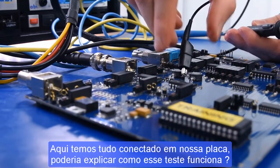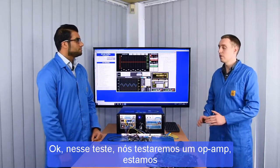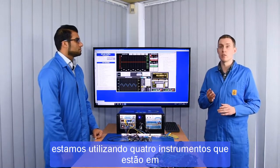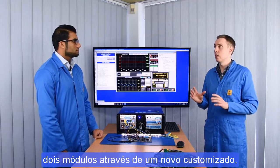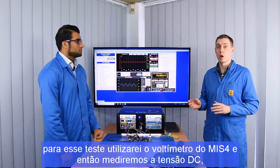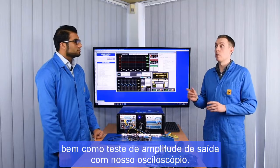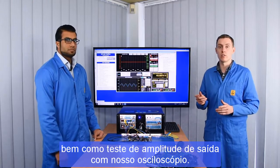So now that we have everything connected to our PCB, can you explain to us what this test is doing? Okay, so in this test we'll be testing an op-amp. We're using a custom instrument. We're using 4 instruments in total from 2 modules combined into 1 custom instrument. We've also added some scripting which will take the measurements from one and then proceed to the next. So in this test I'll be testing the voltage across the device using the voltmeter from the MIS4, and then we'll also be testing the amplitude of the output signal with the oscilloscope as well.